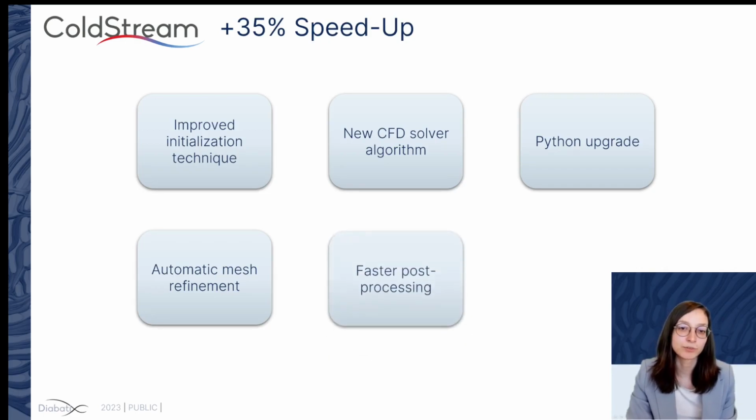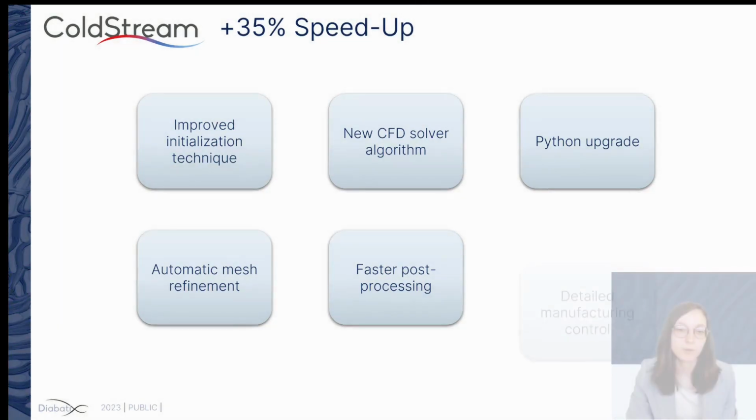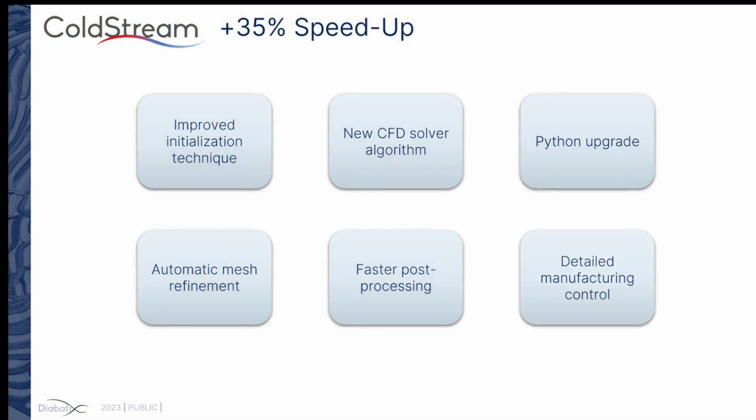Additionally, we have improved our post-processing step to go to a full manufacturable design. Our algorithms work faster and more efficiently when combining different constraints such as minimal feature size, channel width, curvature, and more. We've also added new settings to our manufacturing libraries. For 3D printing, for example, we have added overhang angles, unsupported cantilever lengths, and unsupported bridge lengths, all of this to avoid additional steps after design delivery.